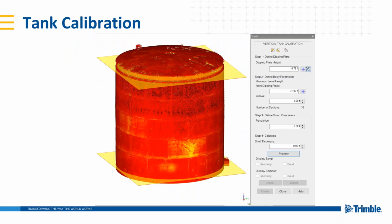Now, when we look at tank calibration, we've got a separate set of tools for tank calibration. Within these tools, you can see the UI here. You'll go in and define the position of the dipping plate by picking a point, or you could do a best fit flat plane to these dipping points, these dipping plates. You can also define the maximum level. You can type in a value, or you can physically click on the point cloud of the tank to define this. And then you can set an interval. You could think of these as virtual strapping, how often you're going to check the circumference of the tank, starting at the dipping plate and moving up to that maximum level. Then we'll also calculate below the dipping plate. That will all be considered the sump area, and we'll create a volume on that as well.